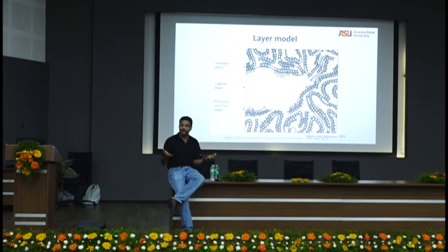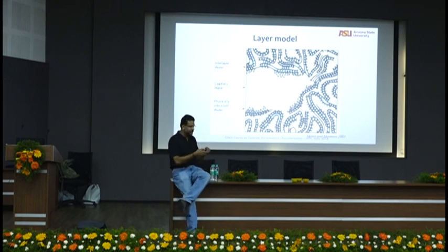You guys know about capillary surface tension, right? So there is a lot of surface tension force between water and the walls of the capillary. You have done the test tube experiment for surface tension, right? There's a lot of force between water molecules and the wall of the pores. You need to give even more energy to escape. So at 100 degrees Celsius, 105 as per your standards, all the water in the capillary pores will go away.